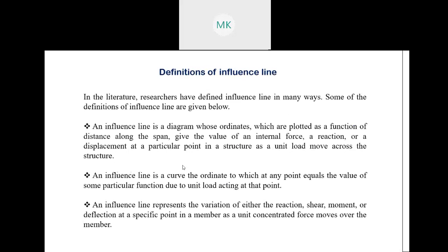There are so many definitions by different researchers. So here you see, an influence line is a diagram whose coordinates, which are plotted as a function of distance along the span, give the values of an internal force, a reaction, or a displacement at a particular point in a structure as a unit load moves across the structure.